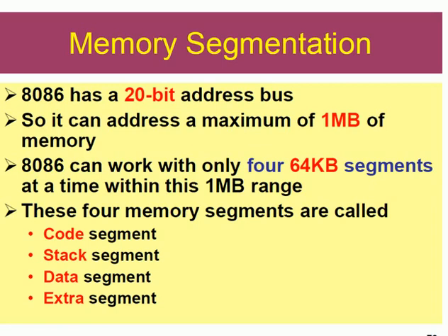H is identified by hexadecimal. And then the stack segment register is only used for stack operations, push and then pop. The starting address of the stack segment register is 50000H to 5FFFFH. And the last one is the extra segment register. The starting address of the extra segment register is 70000H to 7FFFFH. The total memory is 1 MB. The address range of the memory is 00000H to FFFFFH. 20 address lines are used in the 8086 microprocessor.